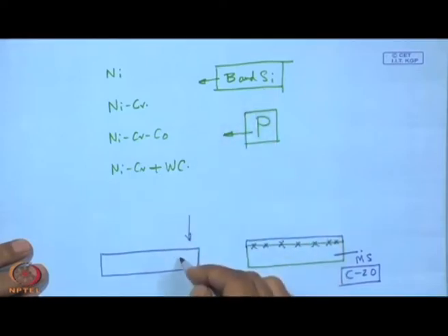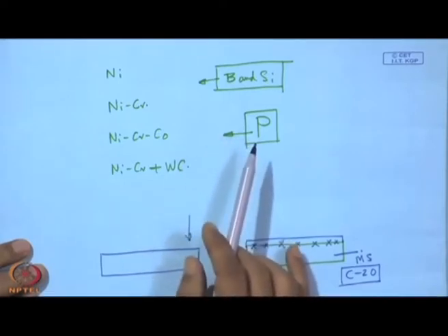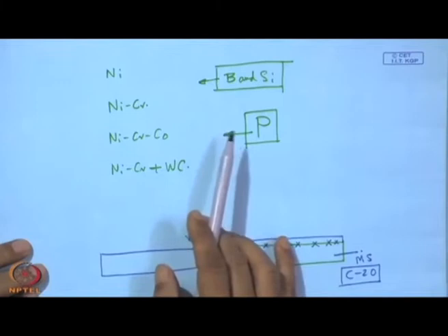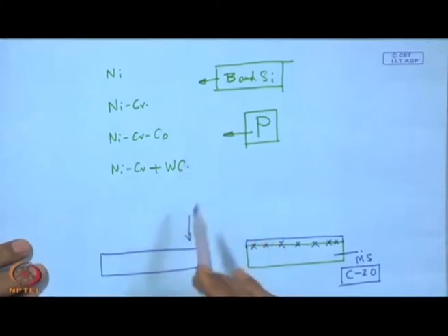So, iron will be reduced again to metallic iron, and those oxides can escape just like a volatile oxide. This is the second important role, for removing the oxide from this low carbon steel substrate.